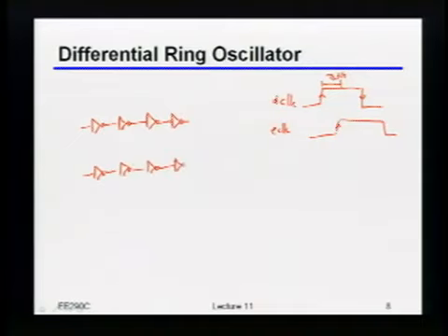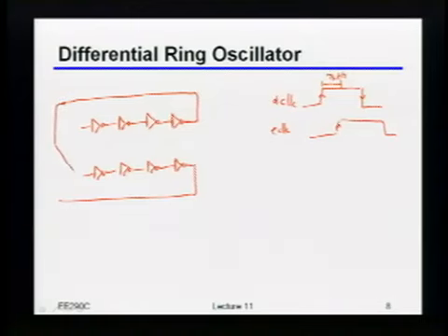The basic idea is that if I take, let's say, 2 chains of 4 inverters, and somehow magically I know that this is inverted from this, then when I take the feedback, normally if I had 4 inverters in a row and I just directly tied the feedback, it would just latch, right? But if I know that these 2 chains are inverted from each other, then what I can do is just cross over, right? And now this thing should indeed oscillate with an even number of stages.